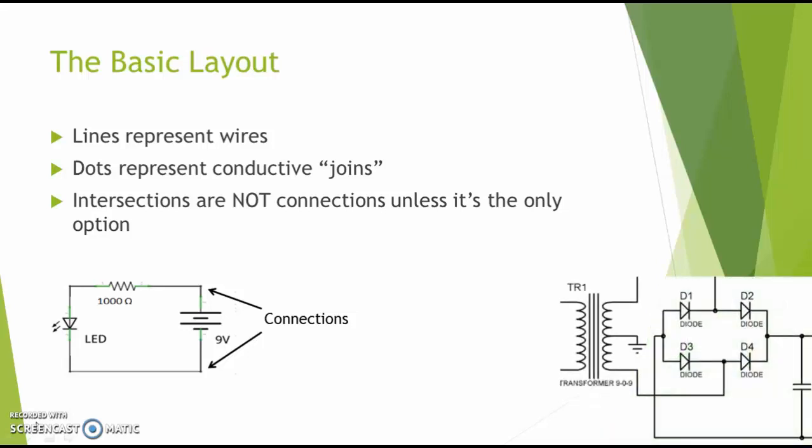Now in contrast, this more complicated circuit has dots representing solder where there's a possibility that it's something else, dots showing connections where there are multiple options. And it also has a place where the wires cross for convenience sake, and there's no dot. There's no connection here. This wire is crossing over the other one, but it's not connected up with it.